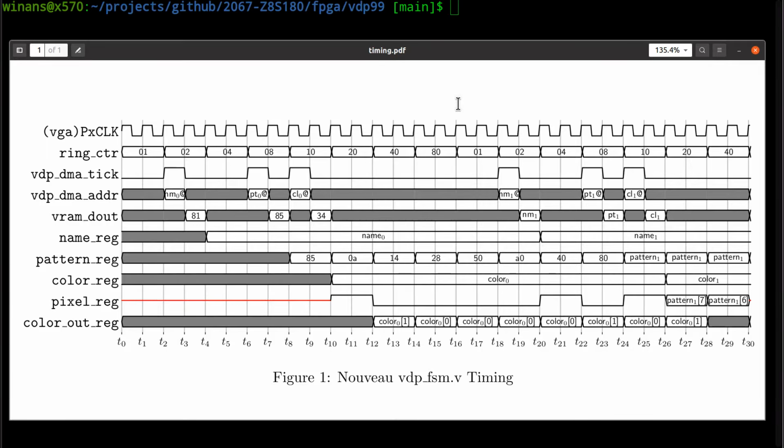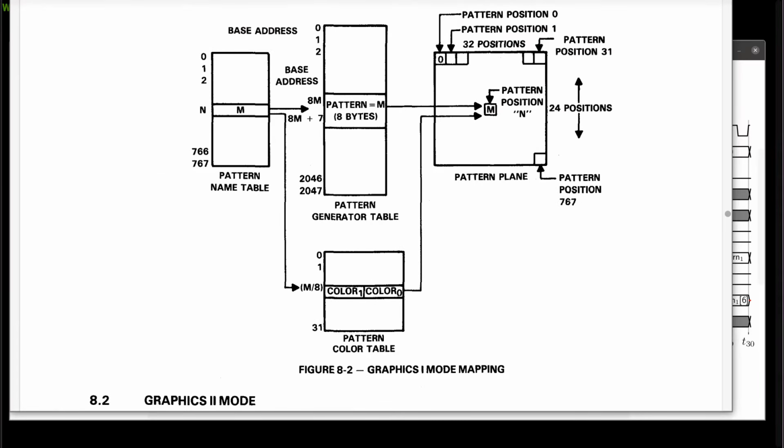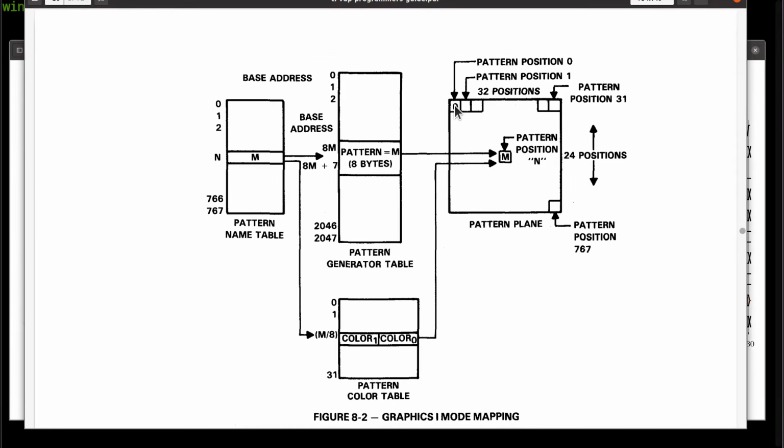So the state machine consumes all that, and when it's time to draw pixels in the active display region, the state machine has to start emitting these pixel colors for as many of the pixels that need to be rendered for the active display. Now, the VGA sync says, let's say I'm in the upper left corner, coordinate 0, 0. When I'm up here at column 0, row 0, I've got tile number 0 up there, okay?